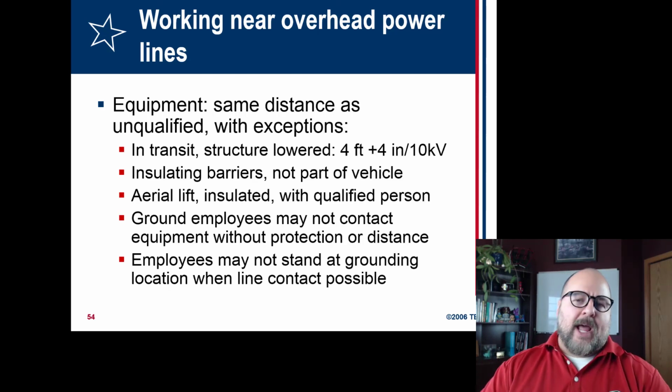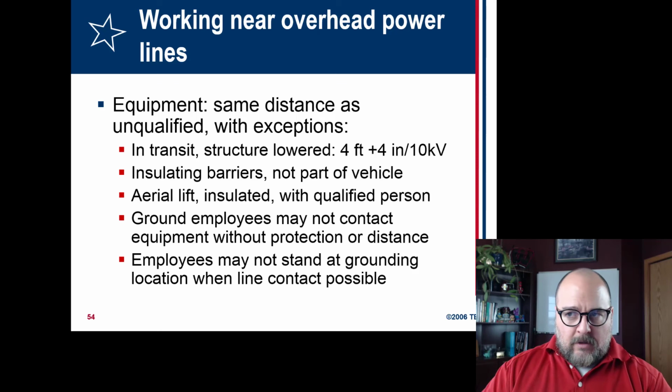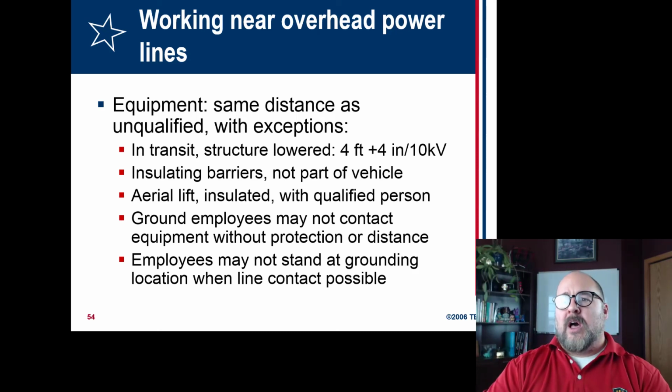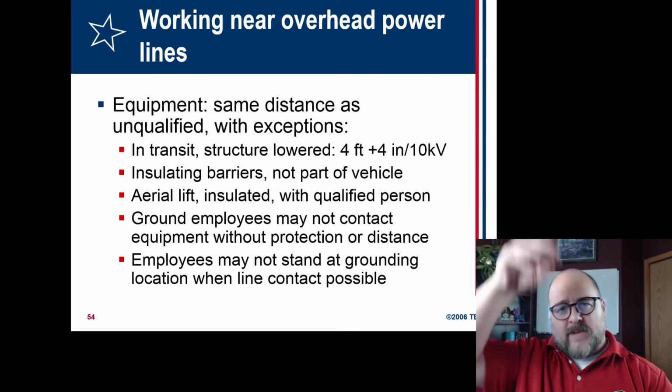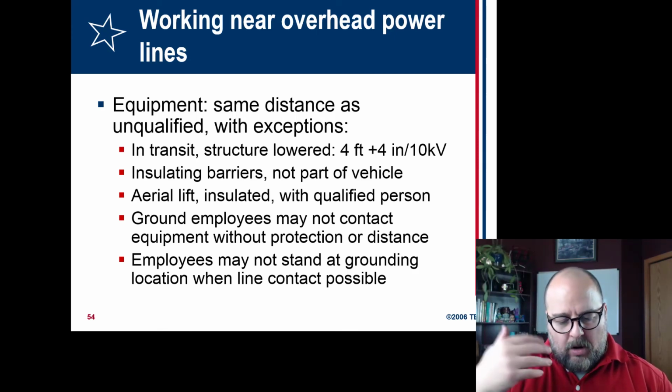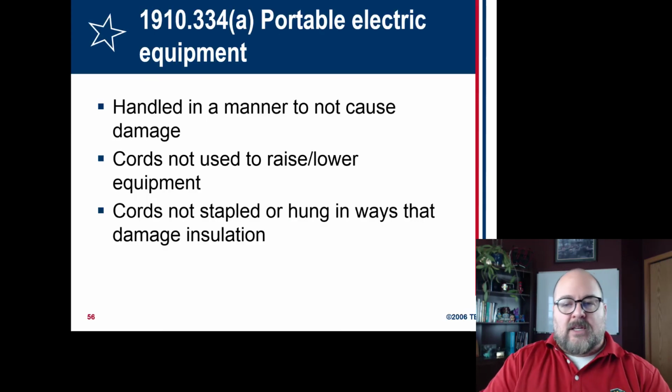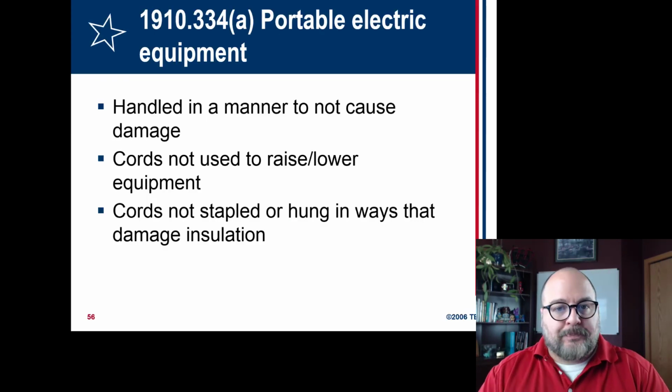It's also a hazard for people who are driving extended arm fork trucks or other sorts of devices that go up and down, because if you are moving and you contact something with a metal chassis, you can energize that chassis and then you're just getting cooked.